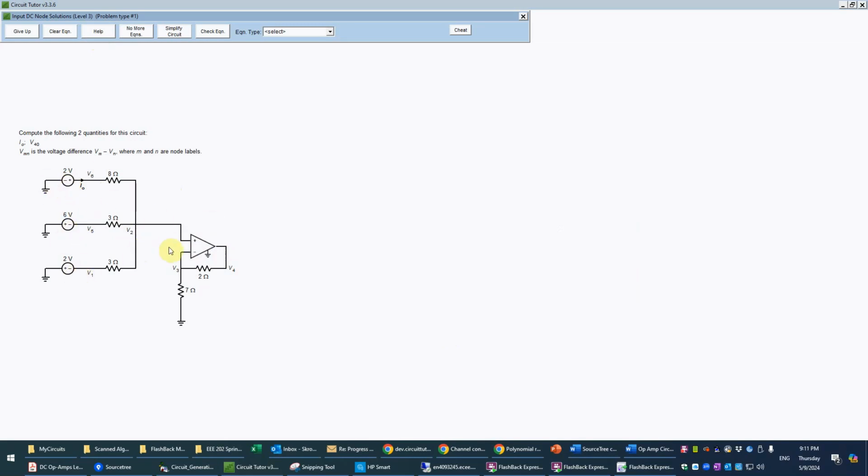This is going to be called a summing amplifier type of circuit, and we'll discuss the function of that a little bit later. It uses a single op amp, and you can see that basically it's forming, in a sense, a type of average of these 3 inputs, which even have different polarities through different resistors, and that input here then goes into basically a non-inverting amplifier configuration that will give us the output voltage.